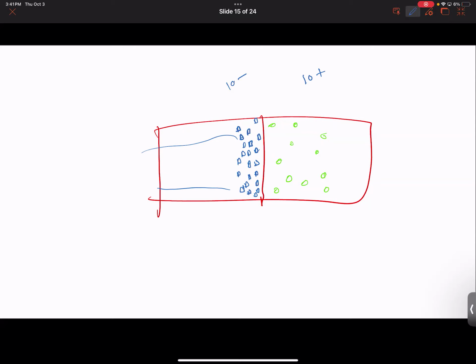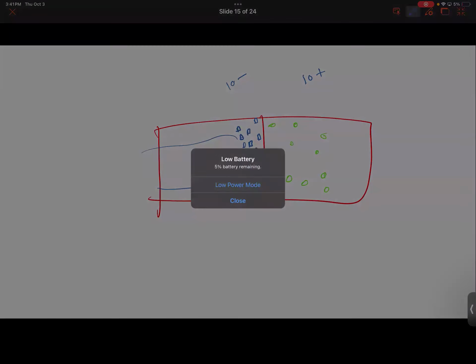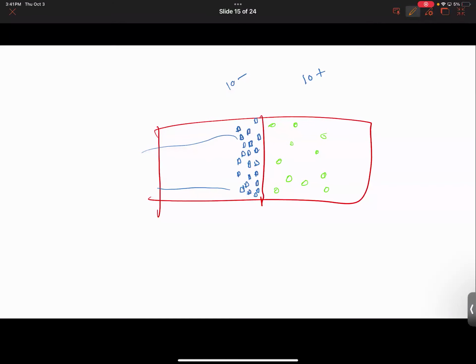When you create a space charge region, it's as if uncovering charges, uncovering 10 positive charges here and 10 negative charges on the other side. Okay, so to uncover 10 positive charges, don't you think you need to dig deeper? Because the charges are so sparse and farther out, you have to go deeper to get 10 charges. Do you guys all agree with it or no? So you have to go deeper to get 10 charges. But here, very close to the surface, you get 10 charges. Do you guys see the reason here?